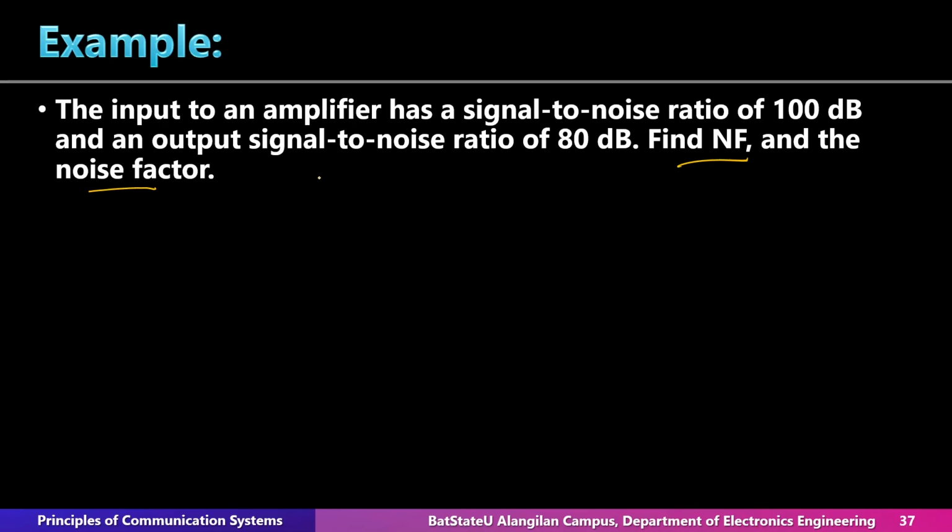Actually, no. You just subtract. Why? Because when your signal-to-noise ratio is already in dB, the signal-to-noise ratio at the input divided by the signal-to-noise ratio at the output gives you the noise figure in dB also.